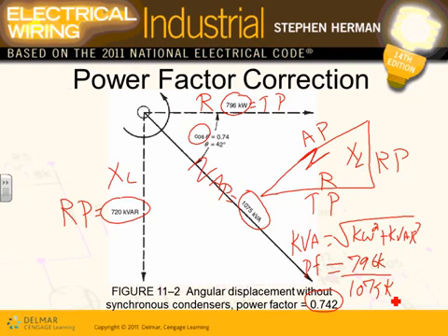So when you correct the power factor, Karen, your job is to neutralize this value. How do you neutralize it? The kVAR, guys, there's capacitive kVAR and inductive kVAR, like positive and negative. They pull in different directions.